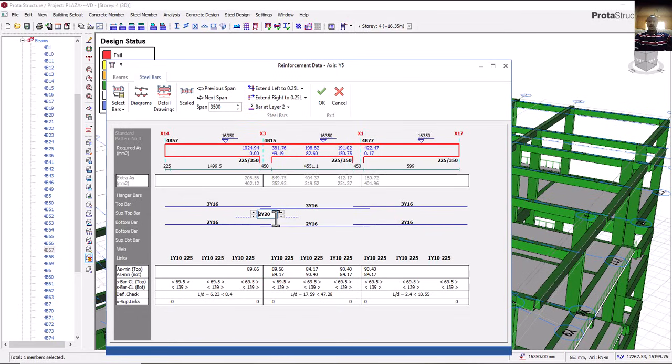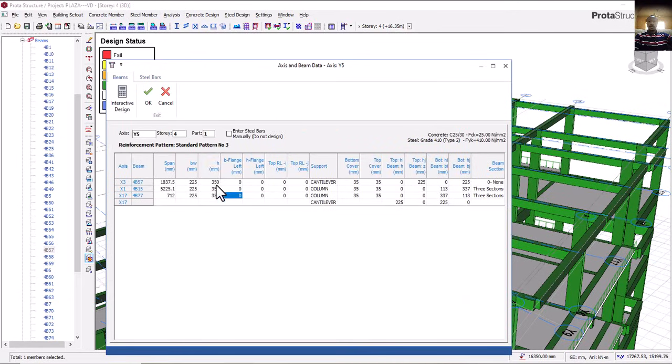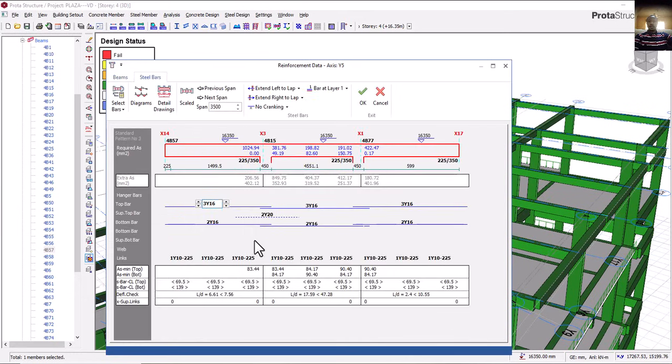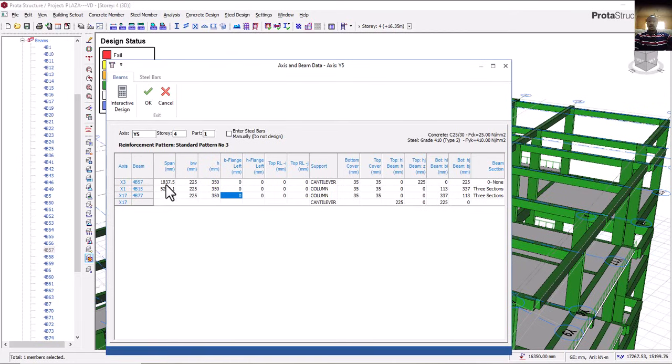Looking at this one, everything's okay, and also here my deflection is 6 against 8. Can you see now? If you come here, 6 against 8, that's about 1 plus. The deflection is not okay for me, so automatically this one I'm going to increase from 350 to 450. Which beam is that? Beam 57. Where's beam 57? Okay, see it here, the first one here. I'll make it 450. I prefer making it 450, and this one 450.